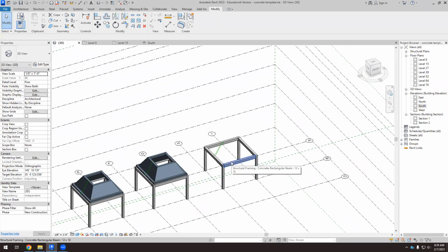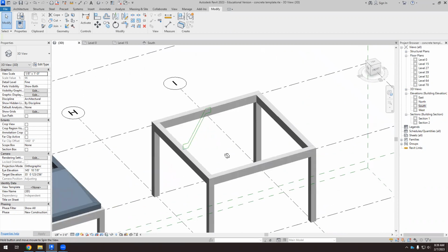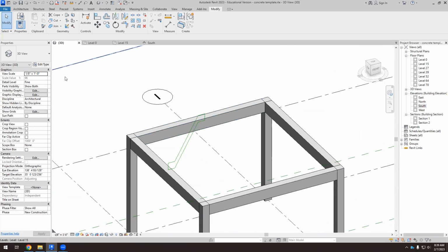So we have used extrusion and then the voids. We have used the sweep option, and I'm going to use revolve. So revolve means that I am going to rotate this or move this about the axis that is in the middle. With the sweep option, I have to select the shape and then the path. Here, I have to select the shape and the axis of the rotation. So I'm going to rotate this about the axis. Okay, so again, I'm going to do it and see what happens.